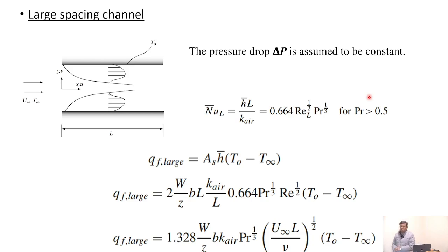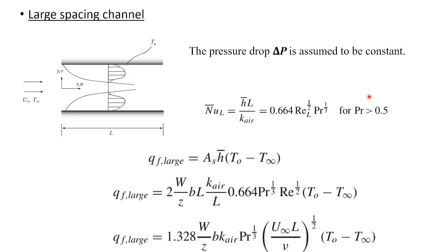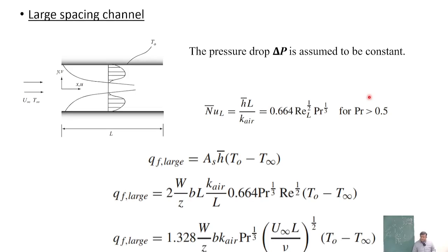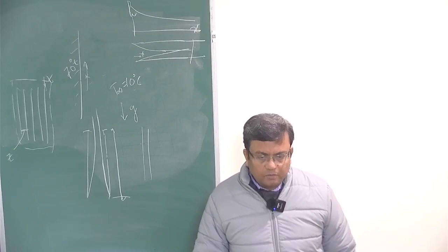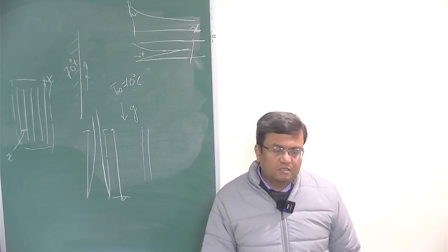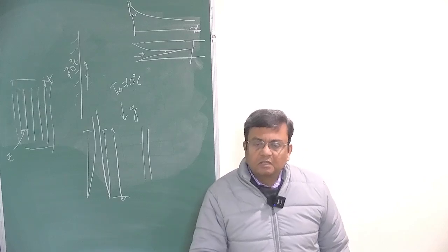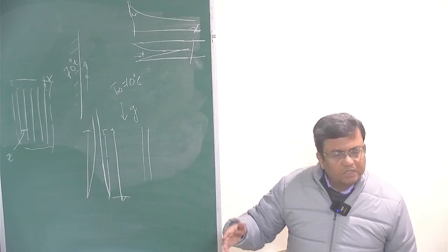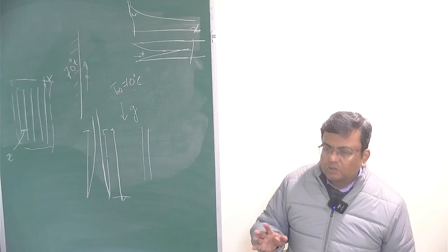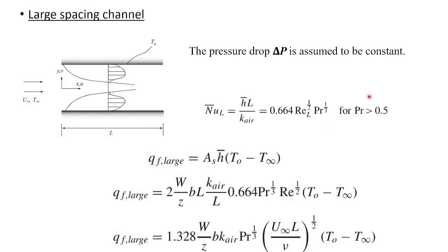If you have to do this thermal design course, you have to have some idea about the numbers. As I said previously also, let's say thermal conductivity, copper is 400 watt per meter Kelvin, aluminum is about 200 watt per meter Kelvin. If you take stainless steel, maybe it's about 15, 17 watt per meter Kelvin, things like that. So similarly, here also you need to know a few numbers. So air at room temperature is about 0.7 Prandtl.